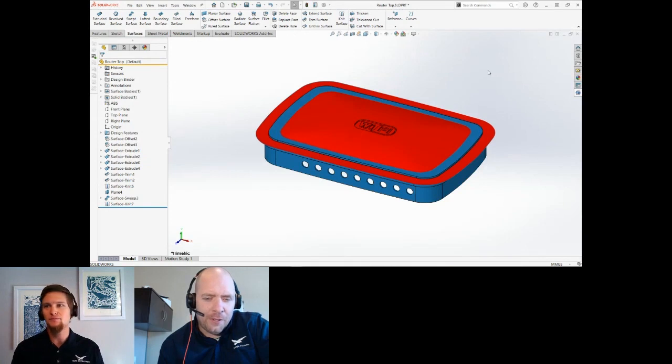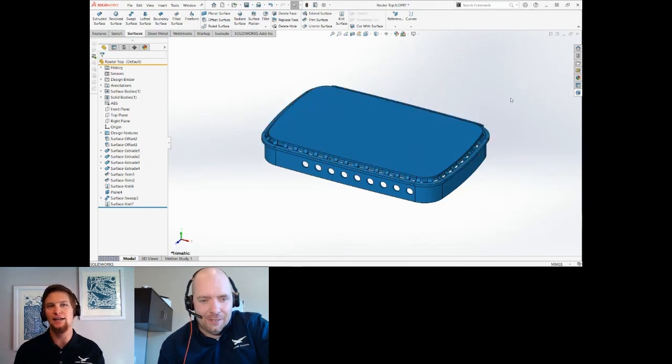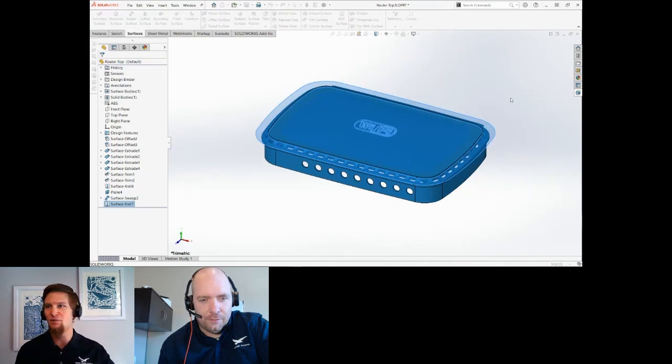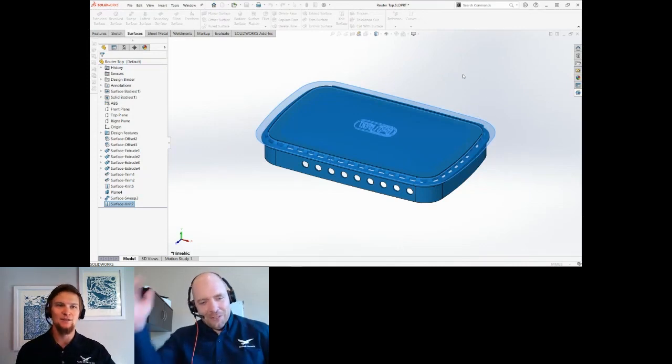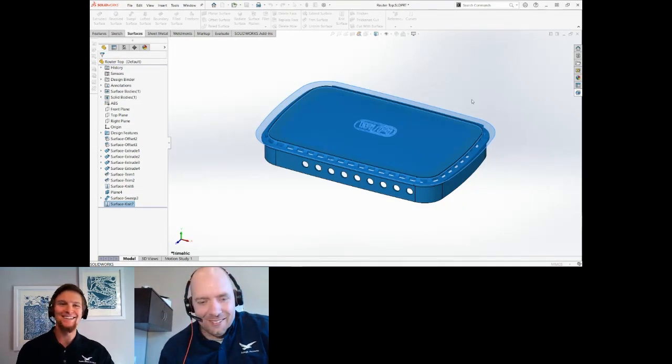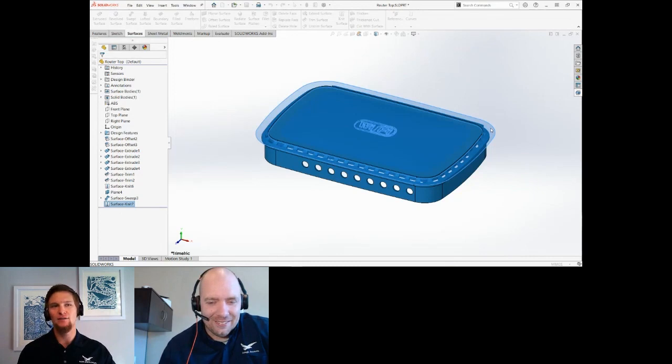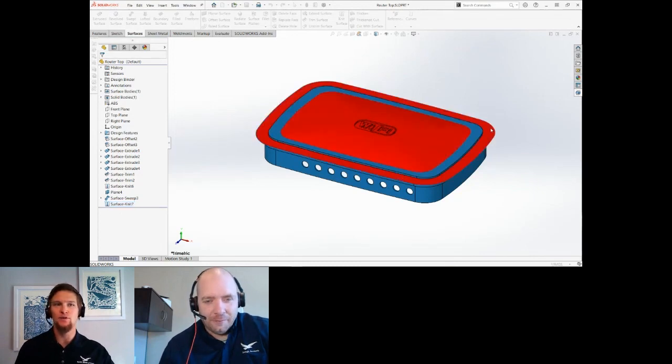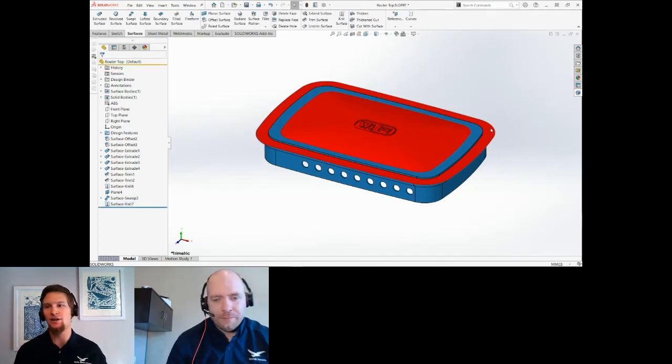Do you remember what control shift tab does? Yeah, let's do that real quick. I'm holding the tab key here, move your cursor around, anything you touch is going to hide. How do I know where those bodies are that I've hidden? If you hold control shift tab, you've got to have some nimble fingers for this. Now that I can see it, you have to click that body while it's in this preview mode. You can bring it back and then let your hand off the keys.